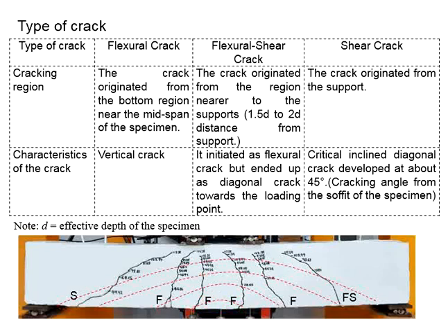The crack happens when the concrete has exceeded its maximum strength. When the stress increases further, a wider region of the concrete has its strength exceeded. Then you will have additional cracks further away from the center. If the crack develops at the midspan, you will expect the crack to go vertically upward. Further away from the center, the crack will become slightly diagonal due to this tensile stress contour.